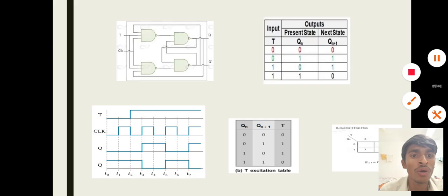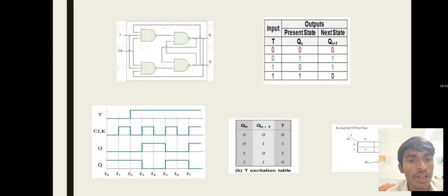Now I will tell you about the key applications of flip-flops. Flip-flops are widely used in counters, frequency dividers, storage registers and shift registers. Flip-flops are used extensively in digital counters that count pulses or events. JK and T flip-flops are commonly used in ripple and synchronous counters. This device sequentially moves through states to represent counting numbers. Flip-flops divide an input clock pulse by factors of two, toggling their output states on clock pulses. This is essential for clock generation circuits and timing applications.